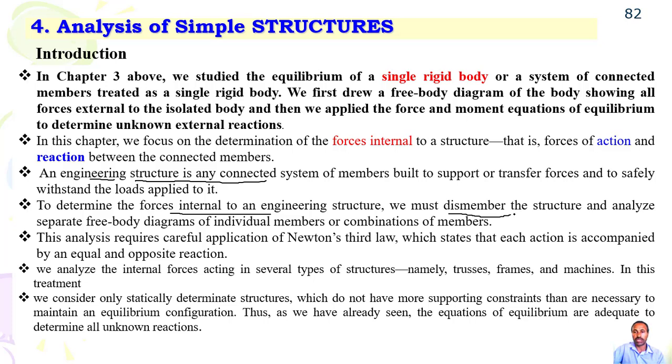the structure and analyze separate free body diagrams of individual connected members or combinations of members. Then we will define whether each force is compressive or tension. This analysis requires careful application of Newton's third law, which states that every action is accompanied by an equal and opposite reaction force. So we have equal forces but opposite in direction, so action and reaction will be used. We analyze the internal forces acting in several types of structures such as trusses, frames, machines, etc.